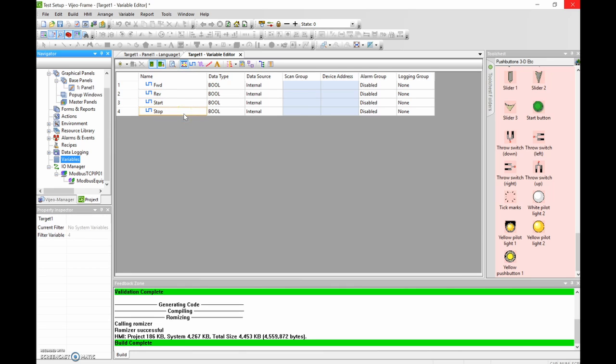And from the previous video, we were using those so that when a push button was pressed on the HMI, then a light on the HMI was able to turn on. So these are all Boolean logic, meaning ones and zeros, and they're little bits of information that we can use internally. Okay, we now need to tie into something that's external of the HMI.